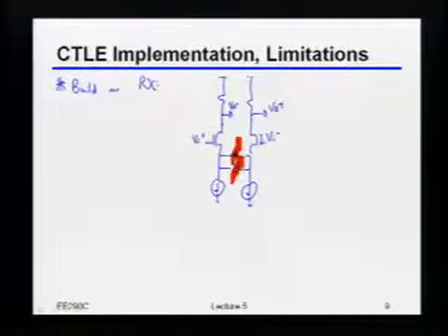What else do you guys think? Yeah. You can only get a 20 dB per decade increase. I mean, if it's more than that. Okay, so you said you can only get 20 dB per decade. The issue I'm getting at is actually closely related to that. But what if I said, no, fine, really, I want you to do more than 20 dB per decade? What do you have to do?